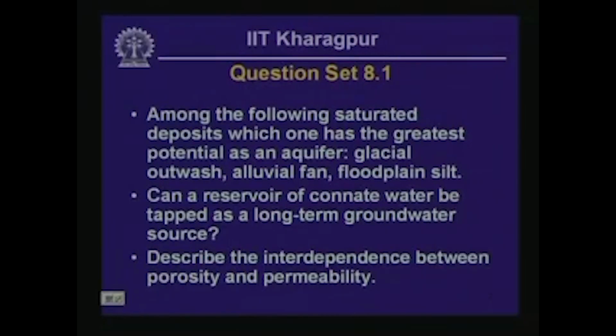If you start tapping connate water, it is not going to last very long before depletion, and because the pore space in which connate water is stored is isolated, it does not really have much option of getting recharged during wet seasons. So connate water does not qualify as a groundwater source to be used over a relatively longer duration.